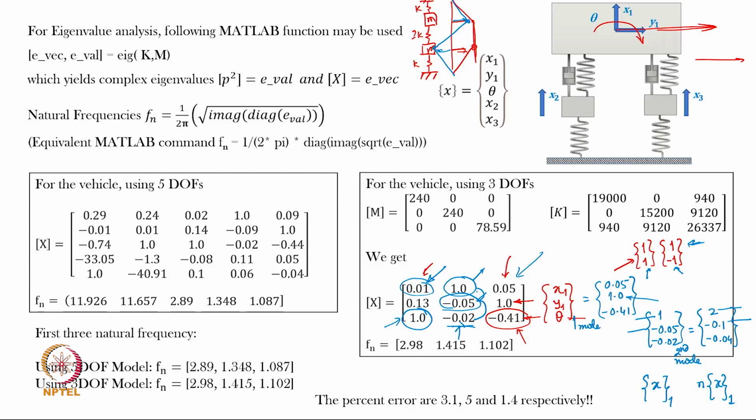So, these numbers should be viewed as the shape or a displacement pattern of the entire system, rather than the physical values representing the final vibratory response. It is not like that. And the other important thing is, each one of them corresponds to the way it vibrates when vibrating at that particular natural frequency.